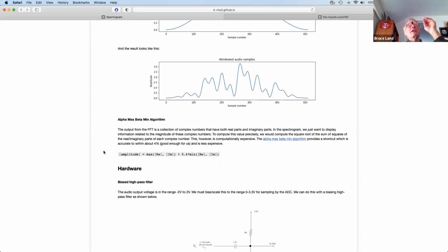And the way you're expanding it is you're applying a Fourier transform to it along a vertical axis, and then clumping time together into windows along the x-axis. And then what's plotted at each point is the output of the FFT at that frequency, which is an amplitude.